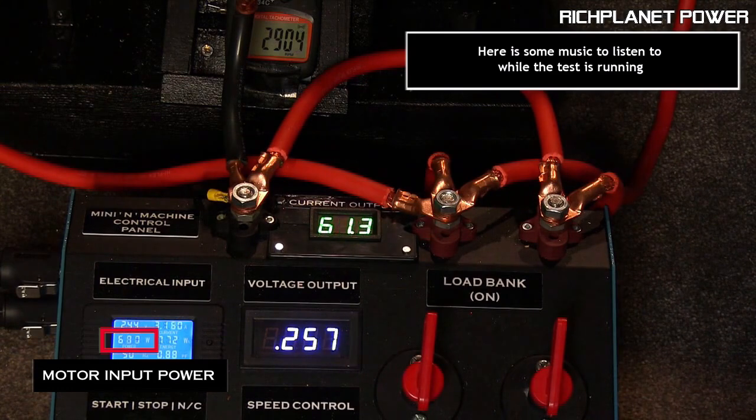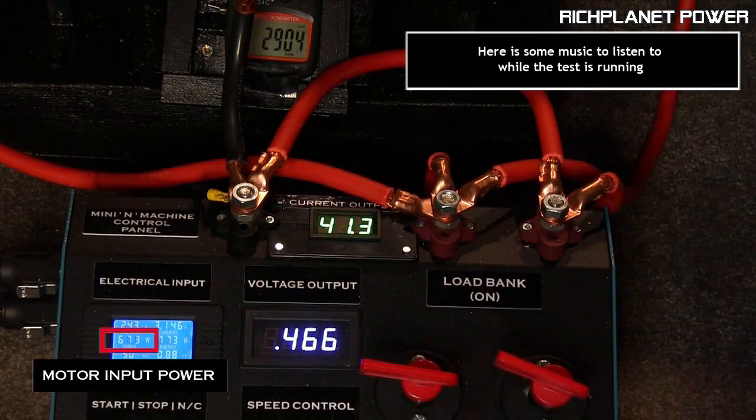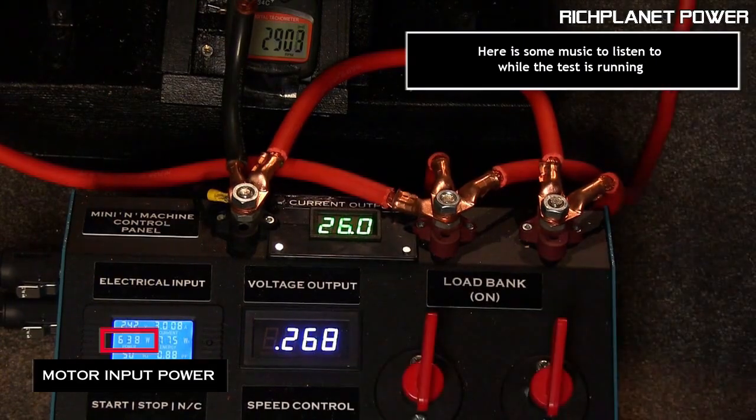Each time these switches were thrown, the input and output parameters were recorded just before and just after the switchover. Using the results from the tests, I plotted points on the graph for the total output power, obtained by multiplying the measured current and the measured output voltage at different values of load.